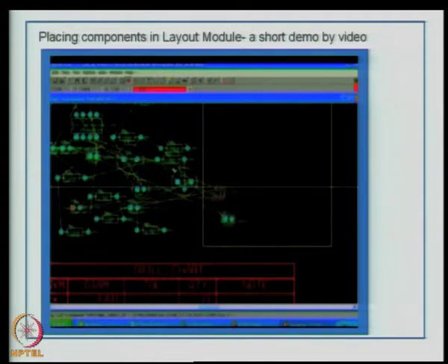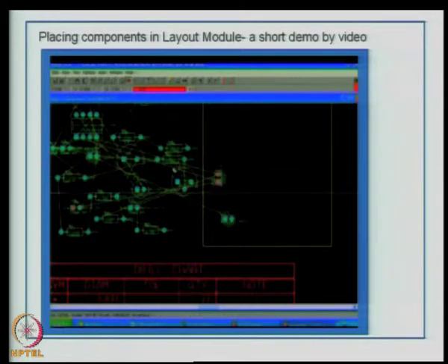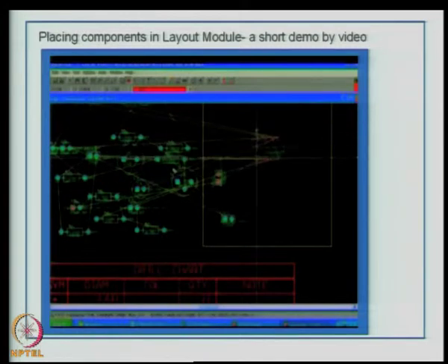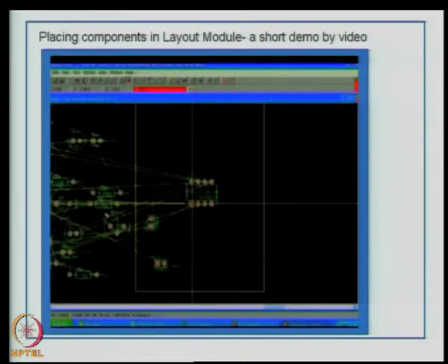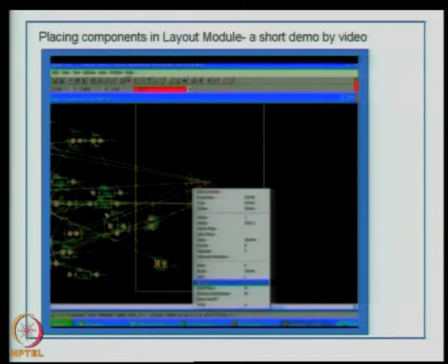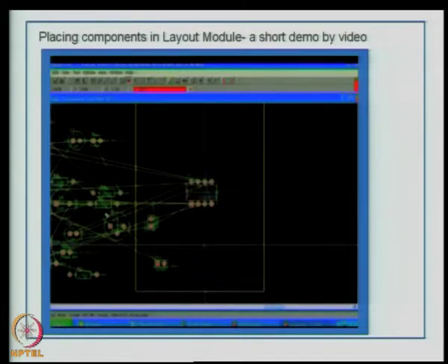So, as a designer, what I would advise you is that you should always try manual placing first, because in the case of connectors, for example, you would like to have connectors at the edges. Now, if you use a complete placement command, you may not get the placement as desired by you.